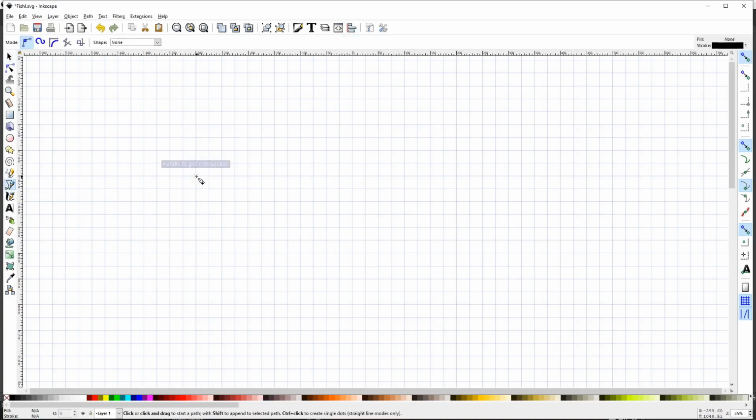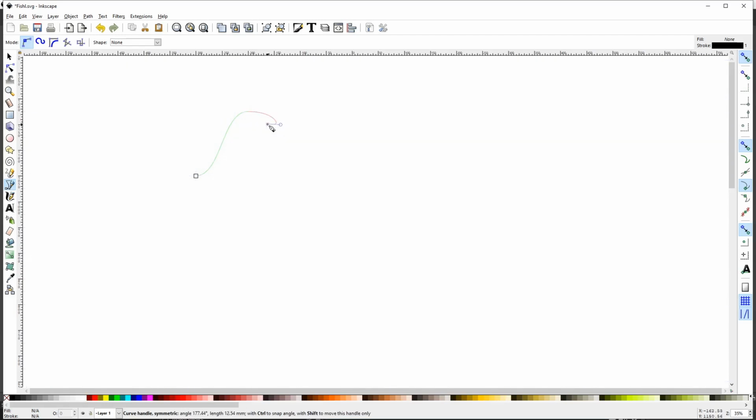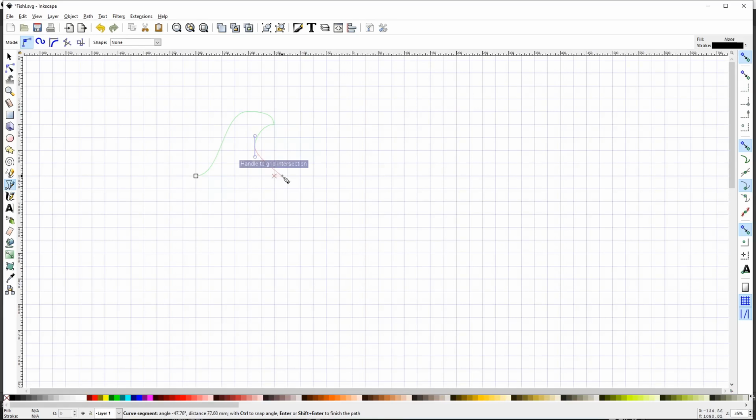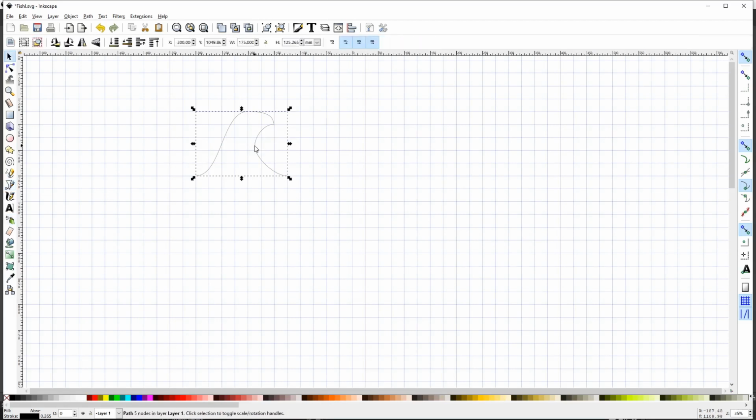So I'm going to just create a shape. So I'm just going to drag a handle. So this is standard Bezier stuff that you've seen before. I'm going to take that down to there. I'm now going to hit the hash key and turn that grid off because I want a bit more freedom. Oops. I'm going to hold shift down and turn that to a point node. Okay, now I want the bottoms to be level with each other, so I'm going to turn the grid back on again. So that's the sort of way you can just bring in the grid and take it away very effectively.